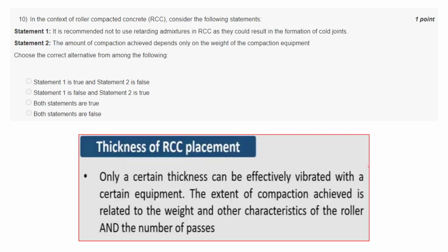Thermal stress will be more than strength, resulting in cracking. That is why the cold joints are formed. So it's recommended to use retarding admixture.